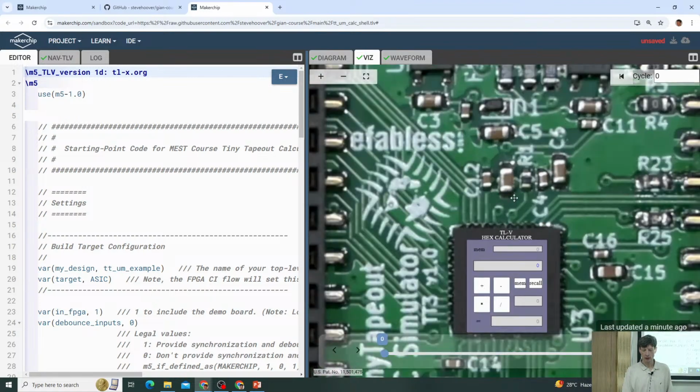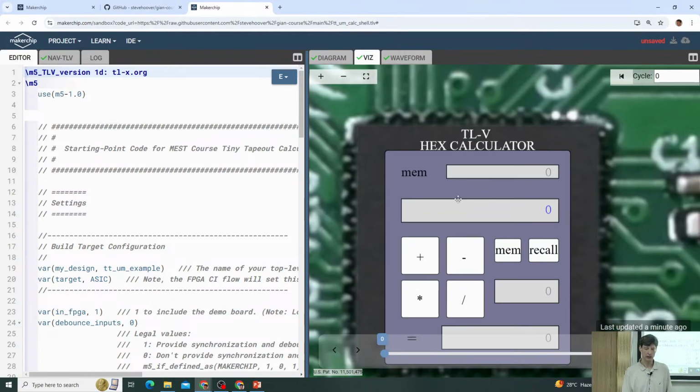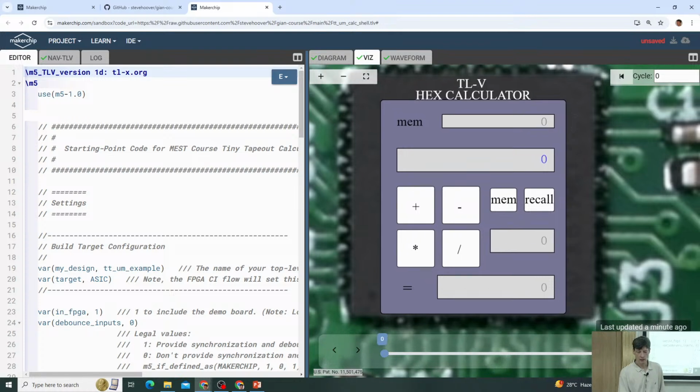And we can zoom in here on the logic that we have in our FPGA. In our case, we have a calculator. This template is providing you the visualization for that calculator. So I can step through in simulation with these controls and see that I'm doing 0 divided by 0, which Verilog defines as a 0. 0 times 0 is 0. If I step through far enough, I might see something interesting. So I'm just going to let this play, doing all these operations on 0, producing 0.